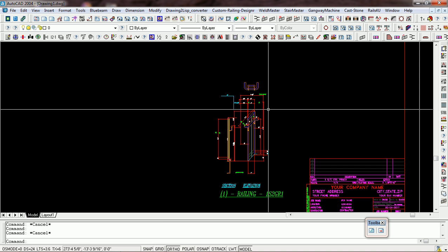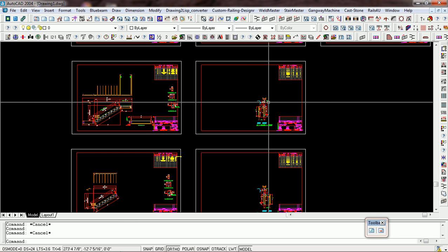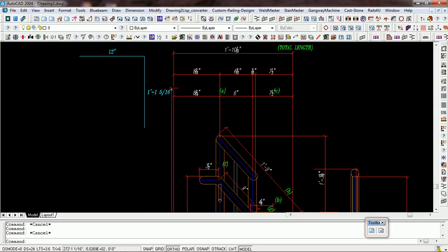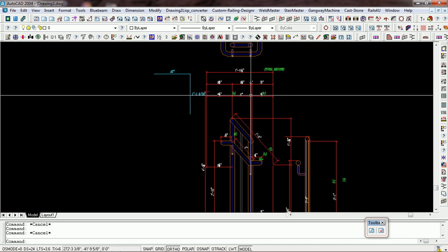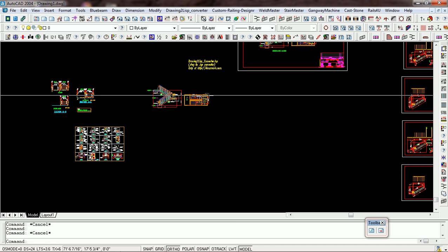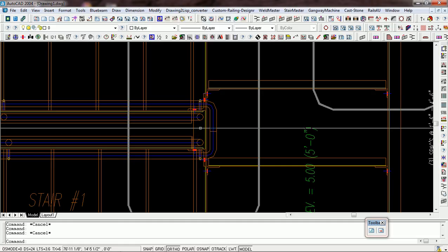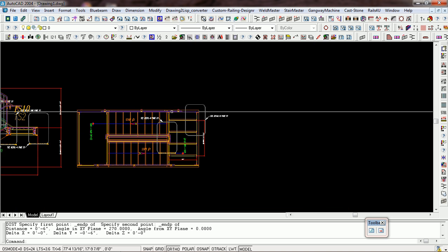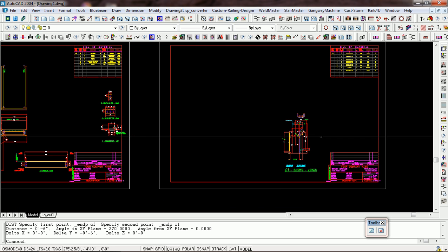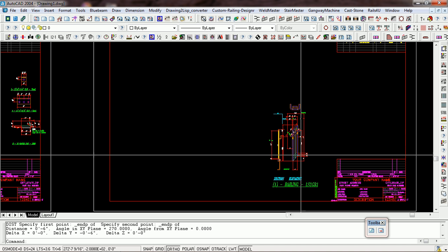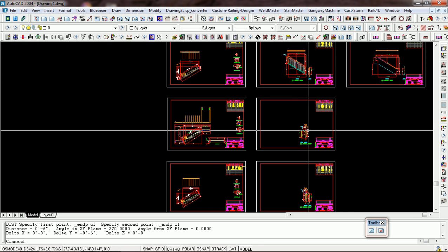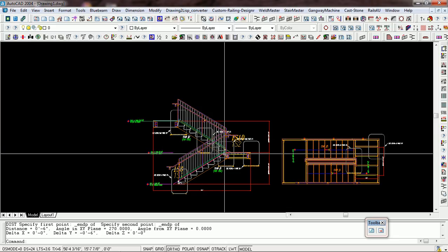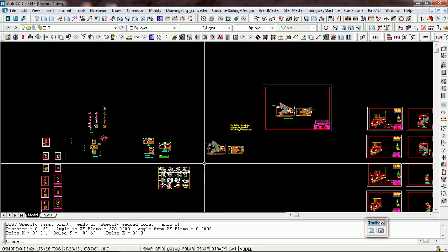It does an end view of the stairs also, and that's an actual real-time end view. So it's 6 inches from the center to center of that railing right there. And if we go back over here, we can just check that. I always put a dimension in here so that they can refer back to there. There's exactly 6 inches. So these are correct. It does a nice job for the end view, and it knows based on how these stairs come together where those points are. So it does a pretty good job of it.